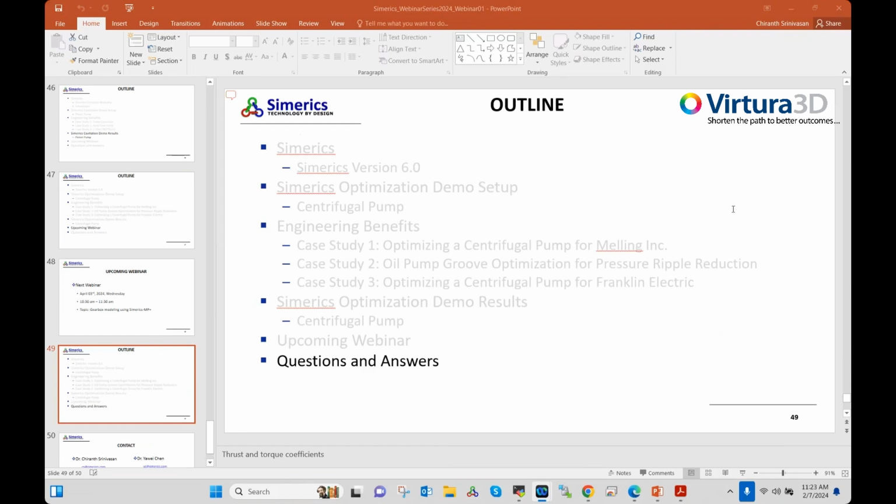From Hannah Boland: in the constant gas model, there is no transport equation solved for the gas or air going in and out of solution. The gas mass fraction is fixed and always free, but the volume fraction varies. It basically simulates small bubbles that are always present in the fluid and never dissolve.